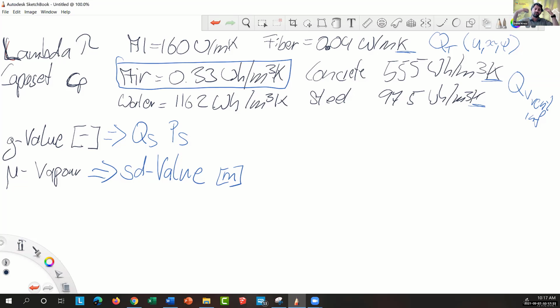And when we speak about investment and having only one cycle a year, seasonal storage starts to be really, really expensive compared to something like a little battery, like your Powerwall in your house, that has a cycle every day. So you could have up to 350 cycles. The economic implementation of short-term storage is far easier than long-term storage.